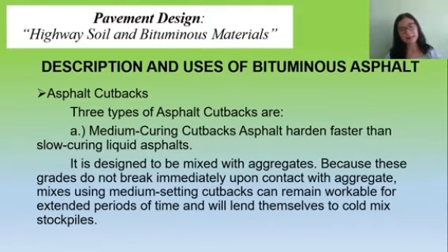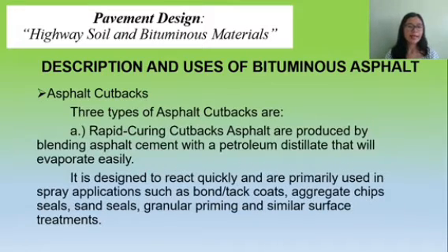Next, we have the medium curing cutback asphalt, which hardens faster than slow curing material. It is designed to mix with aggregates because these grades do not break immediately upon contact with aggregate. Mixes using medium setting cutback can remain workable for extended periods of time and lend themselves to cold mix stockpiles. So in other words, medium curing is better than slow curing. It's faster also.